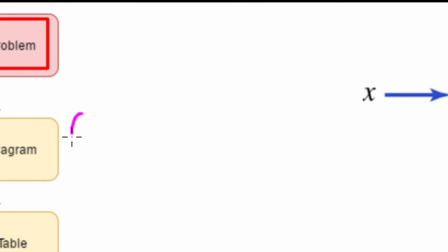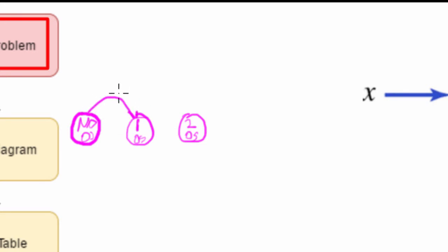So let's see. No zeros. And then I'm going to try to find 1 0. And then I'm going to go to the state where I found 2 zeros. Okay, if I find a 0, I go to here. And I output a 0, because this is Mealy. If I find a 1, I stay here. And I output a 0.